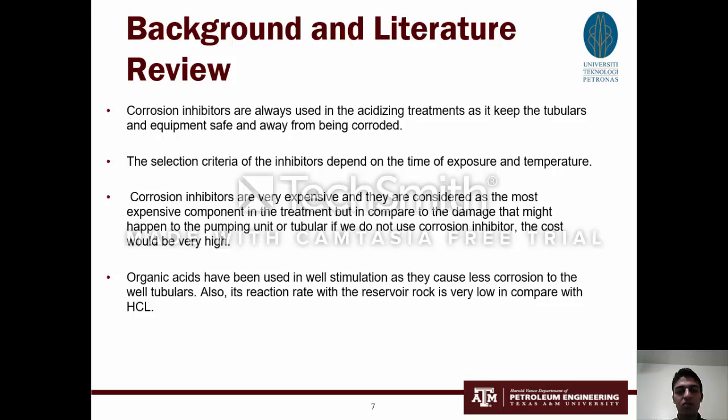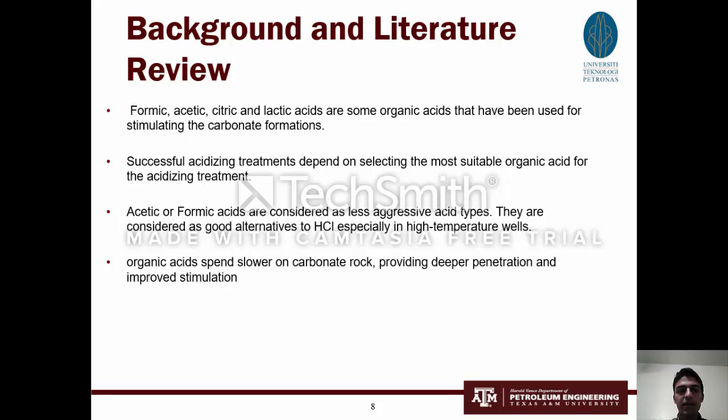Organic acids have been used in well stimulation as they cause low corrosion to the well tubulars. Also, their reaction rates with the reservoir rock are very low compared with HCl. Formic, acetic, and lactic acids are some organic acids that have been used for stimulating carbonate formations.